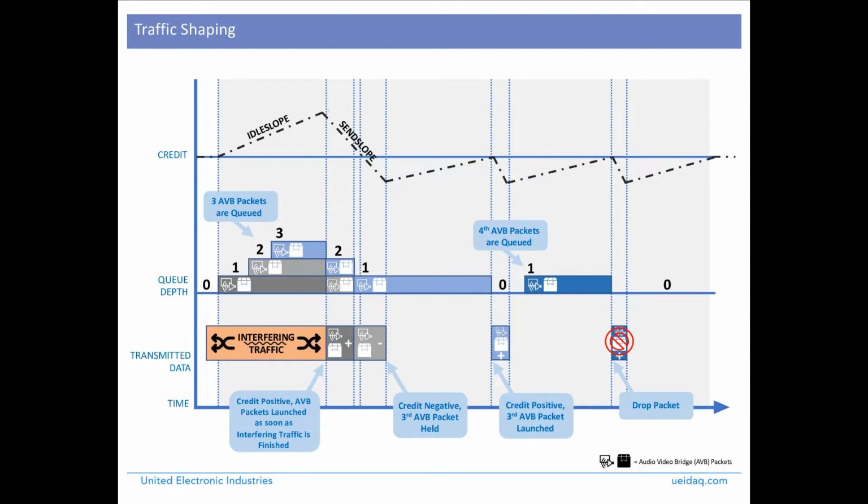Assuming there is regular traffic, you should try dropping a preempted packet. Your device should be expecting it, but it doesn't arrive. Now what? More stress testing can include misshapen traffic. Traffic like low priority packets requiring high bandwidth or high priority packets requiring low bandwidth.